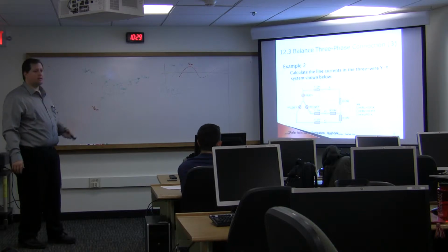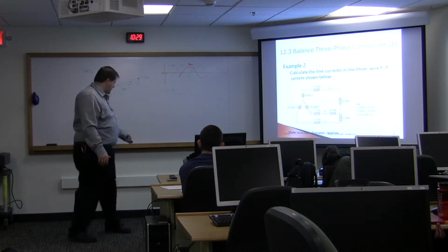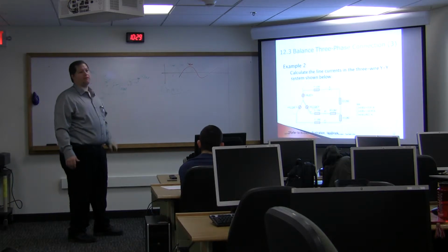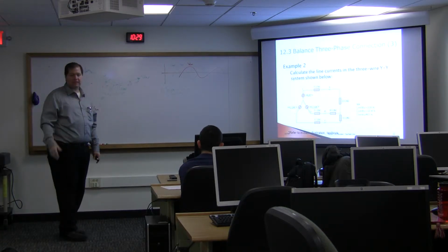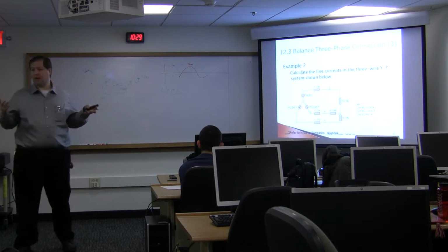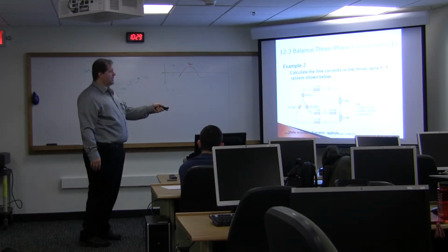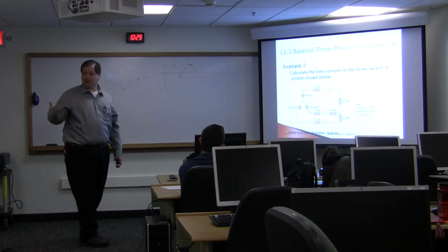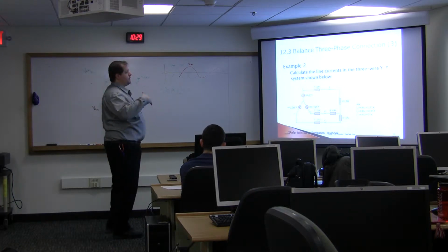If I'm describing a power distribution system, I know the voltage is 110 volts coming out of the wall socket, and I can determine whatever the impedance of the lines getting up to that point would be. There's some resistance. In this case, there's a negative j2, meaning there's some small effective capacitance as well. And then I'm connecting this to an impedance that has some resistance, and since it's a plus j8, it has some effective inductance to it. So I can determine this for each one of these.